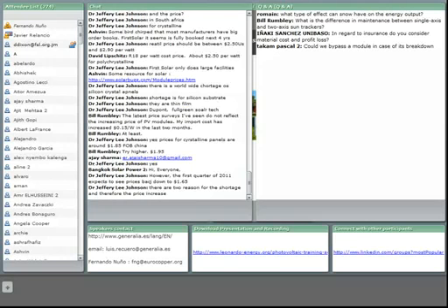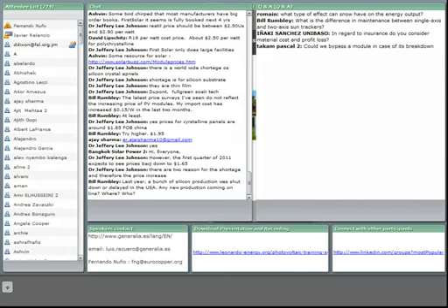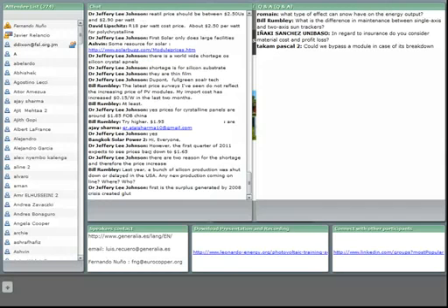So if we have less voltage in a module array, in a module series, than in others, we can even produce damage to the rest of the modules within that area of the installation, because that series will have less voltage than the rest of the series connected in parallel. So we have to be careful with this kind of solution, because the best solution could be doing a bypass on the whole series in order to have the same voltage in all the area.